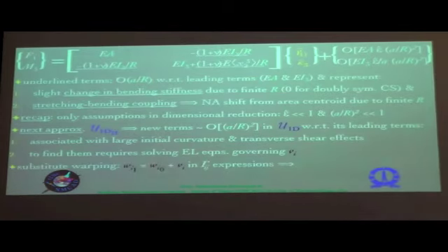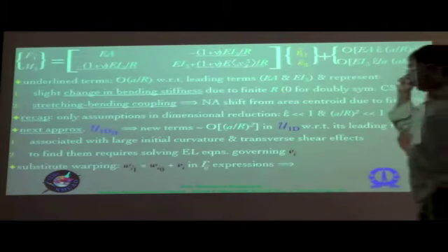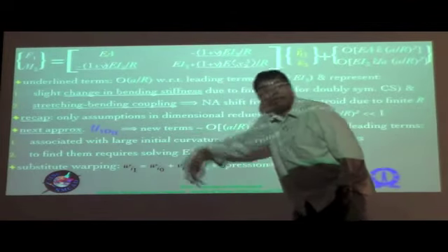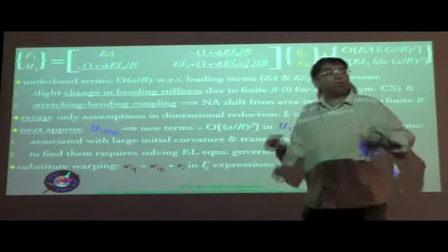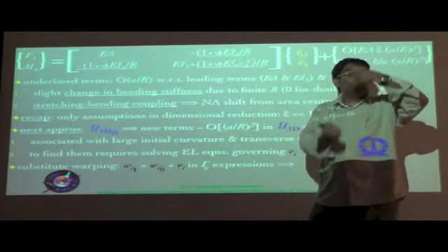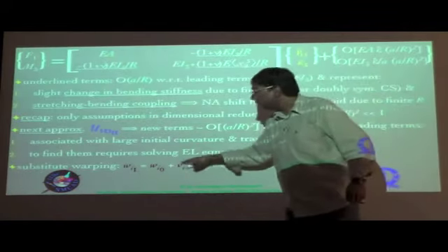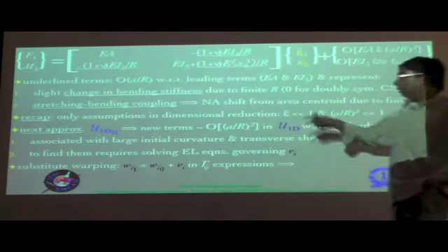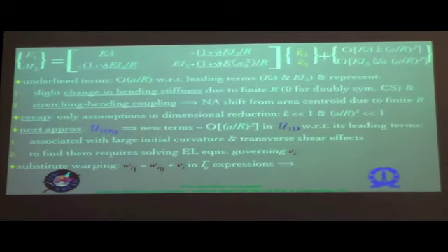you will get the next order correction, and from that you will be able to determine these two corrections that we're talking about. And substitute the warping, which is the first order warping, which is the classical theory, whatever warping was there, which was only W2 and W3, the in-plane warping, purely Poisson's effect, and then the VI, which we didn't solve for. That together, if you substitute into the strains and then into the energy, you would get that.